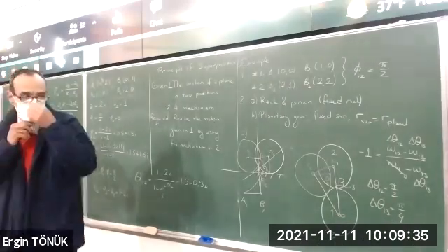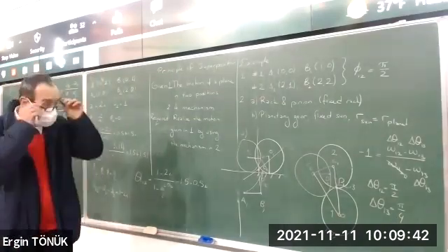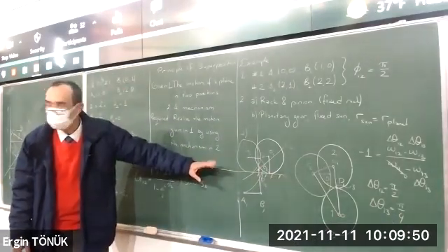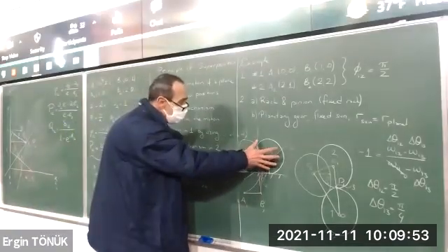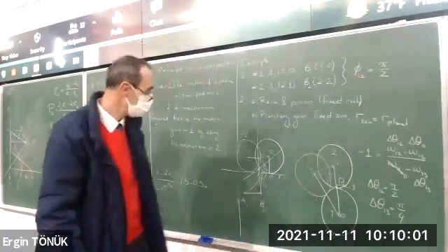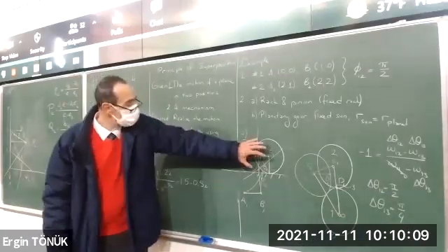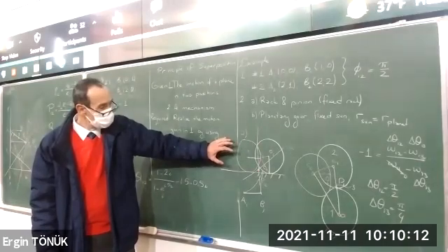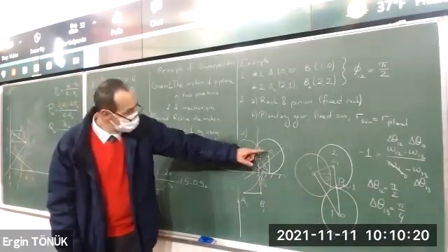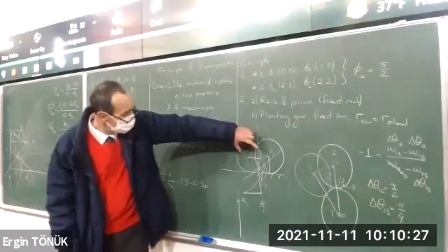I'm sorry. Okay. Now, rack and pinion is the same motion as a cylinder rolling on a straight surface without slipping. Okay. So what I want is this should rotate by 90 degrees, which is the same as this one, in counterclockwise direction. So white one is the first position that I have, and I roll it 90 degrees, so it's going to translate to the left. And actually, you can compute the distance O1, O2, which is radius of the cylinder times pi over 2. Am I right? So you can calculate this distance.